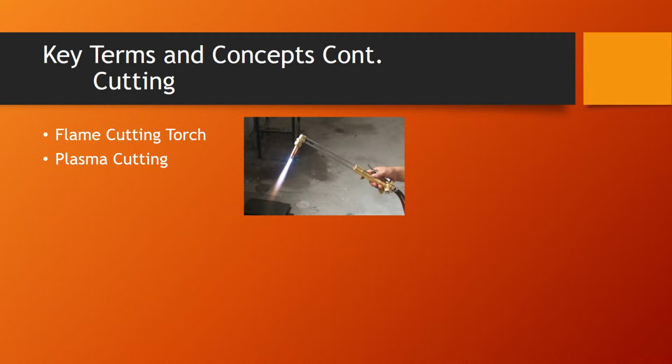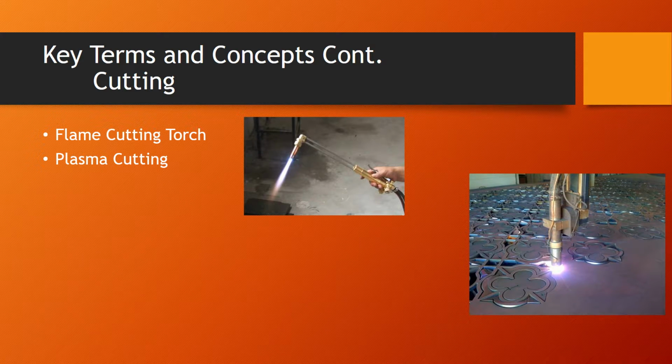Plasma cutting uses electrically charged gases and pressure. Gases create an arc, melting the metal, and then blow away the cut material. Developed in the 1950s for metals that could not be cut by flame torch, like stainless, copper, and aluminum. Laser cutting uses a high-powered laser or light source that passes through a series of mirrors, then can perform items such as cutting, engraving, and even welding.